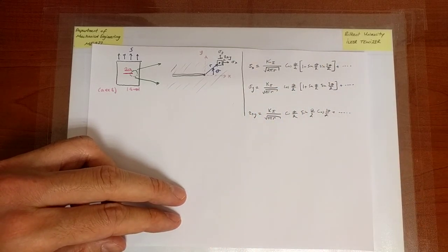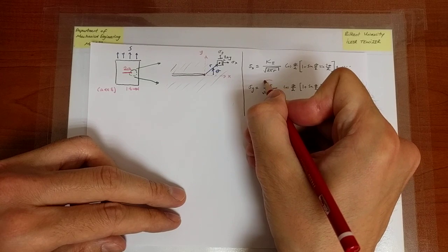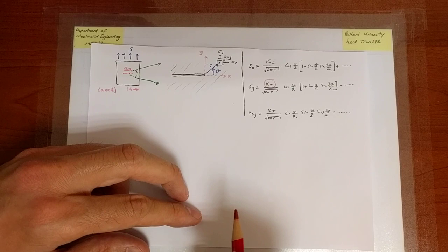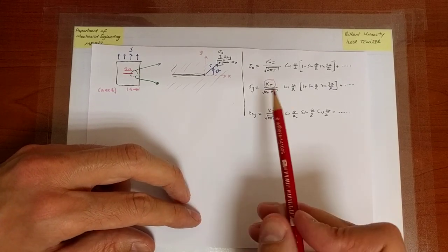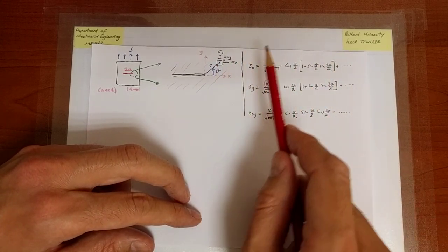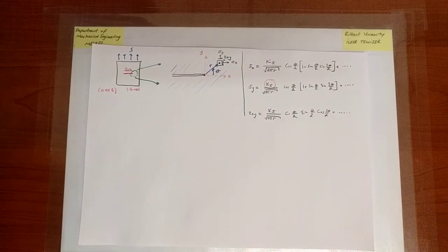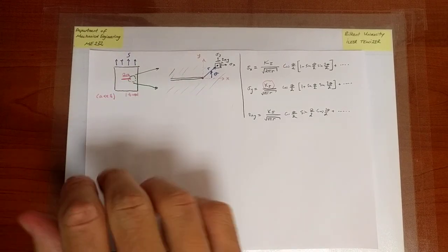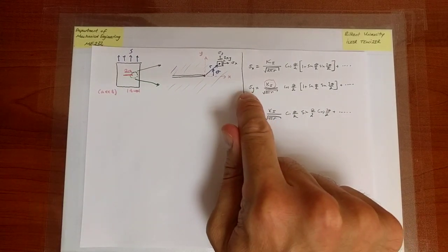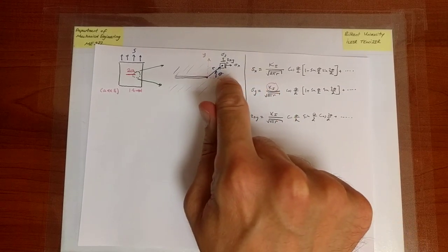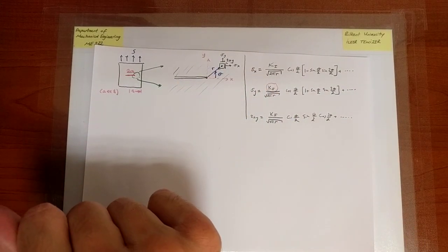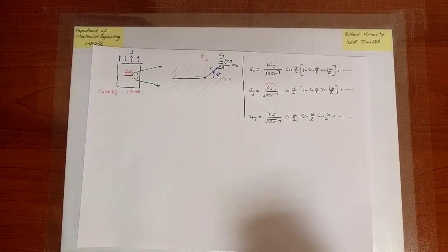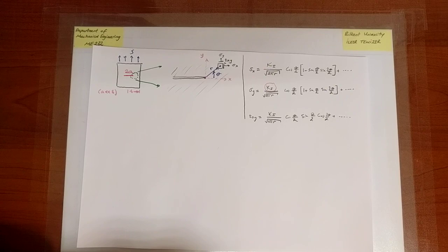Again, ultimately, what we are going to concentrate on is what K1 stands for, what it physically means eventually, and how it will be useful for us. But presently, I'm writing these expressions so that we understand that the stress field at or near the tip of the crack is quite complicated. For instance, for sigma y, r goes to 0 and the stress goes to infinity, but depending on the orientation, theta, the stress components will also change.